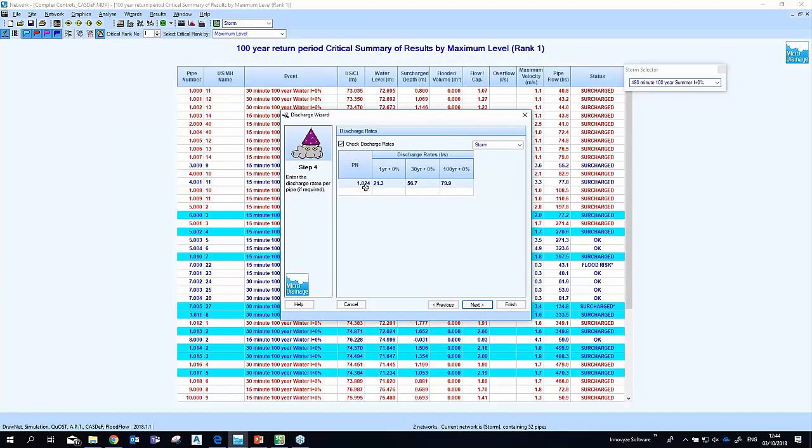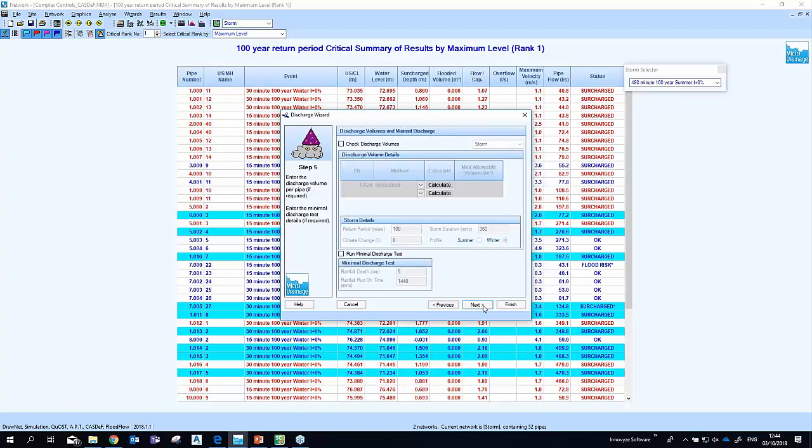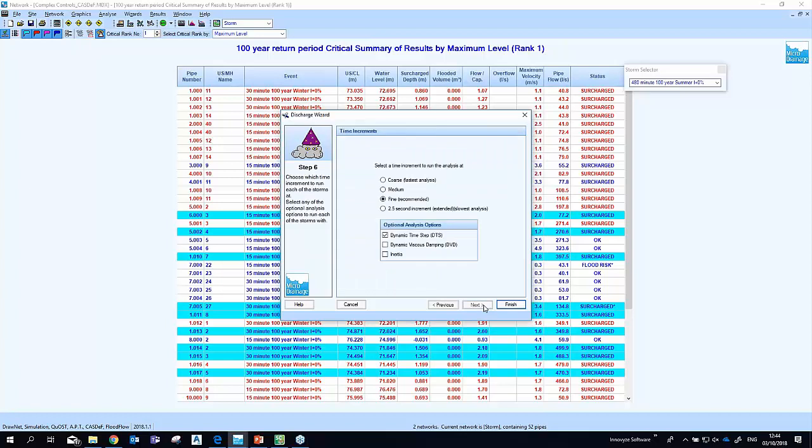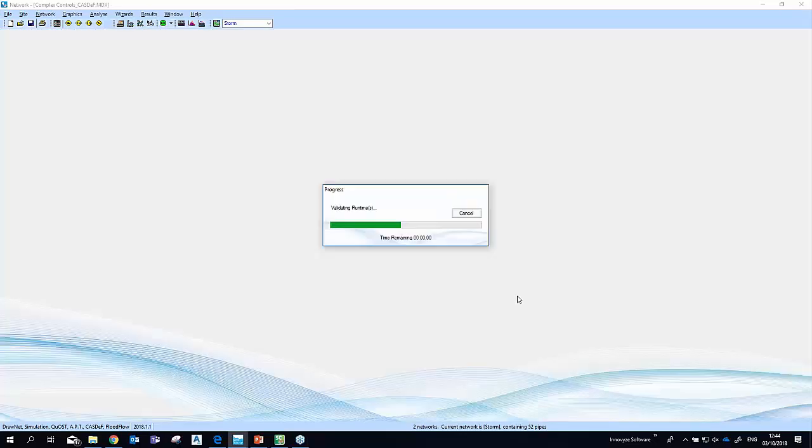So it's going to run through, and I'm telling it the maximum allowable rate in my final pipe, so my outfall, for each selection. I could also include discharge volumes if I wanted to. In this case, I'm just going to do the rates. I'm going to assume we've already answered the volume question, hence we've been allowed multiple different discharge rates. And MicroDrainage will run away now, go off, solve for me those problems, and come back with a nice little report that will hopefully show me 3 big green ticks saying, yeah, well done, Max. You've been able to run all of those different simulations at the different return periods, and it's just doing that post-processing and analysis of the results automatically for me.